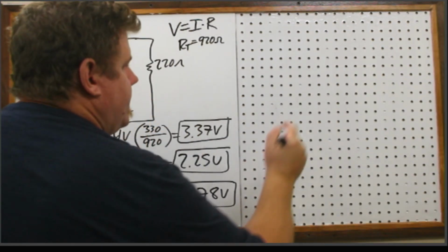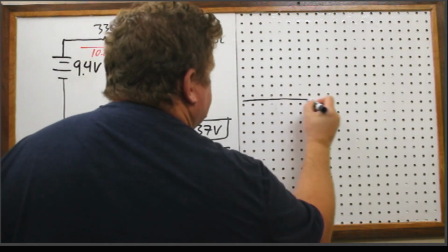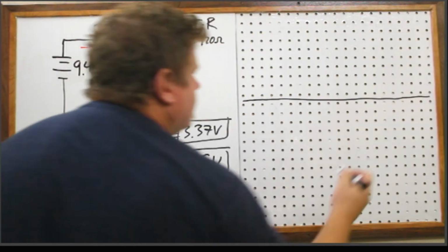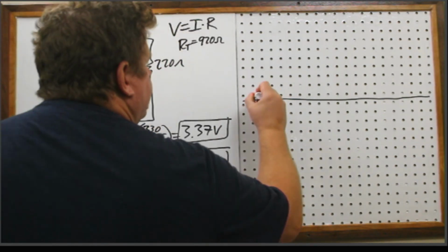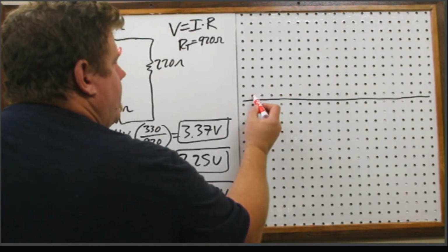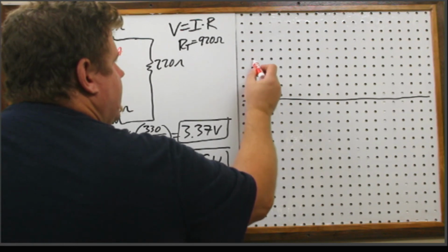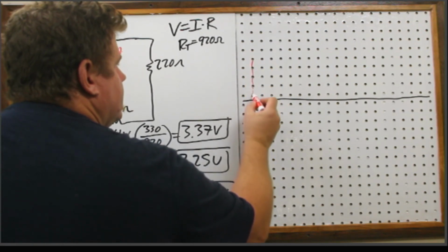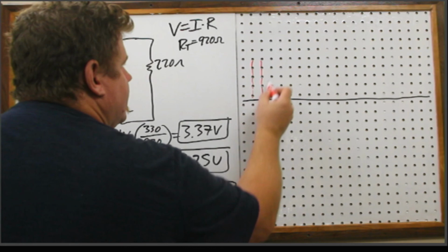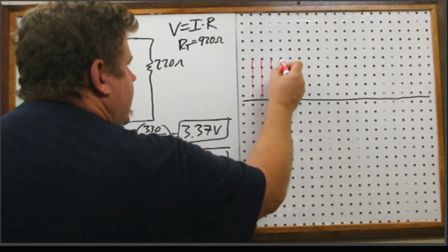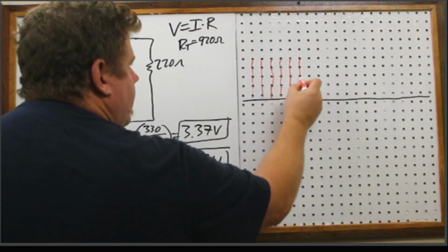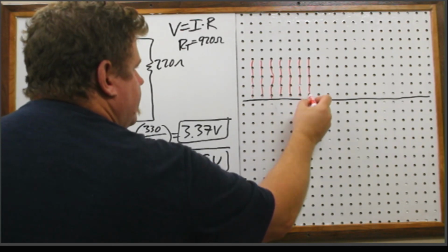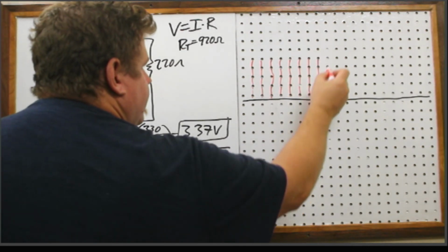Okay, this is going to be my bridge that goes through the middle of the breadboard, okay, which means that, you know, I'm counting up here. 1, 2, 3, 4, 5. Each one of these 5 are connected underneath. This is what I explained in the breadboard video. Okay, I'm not going to go all the way across here, but I'm going to do enough of them just so you get the picture.